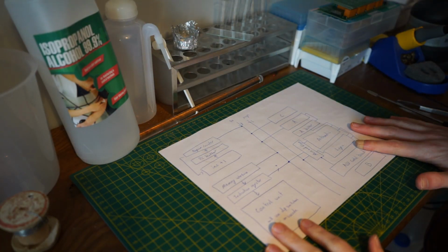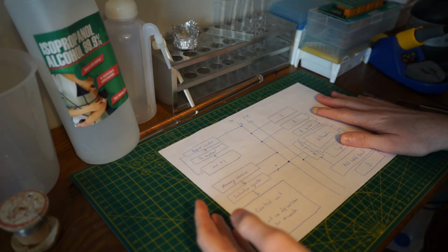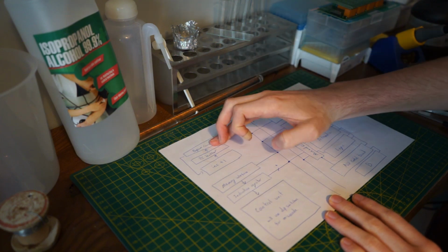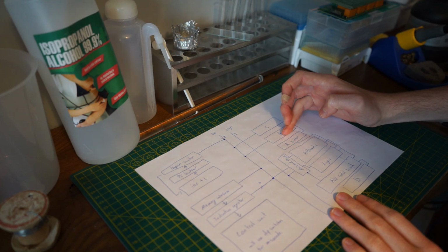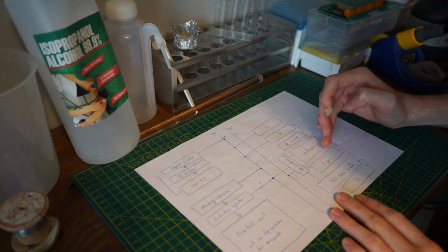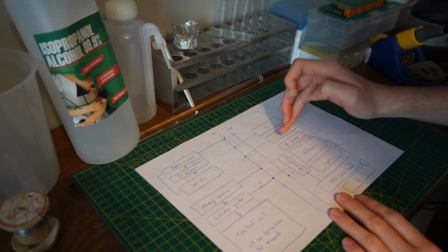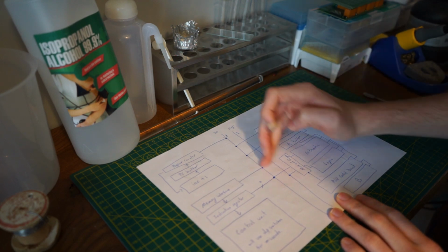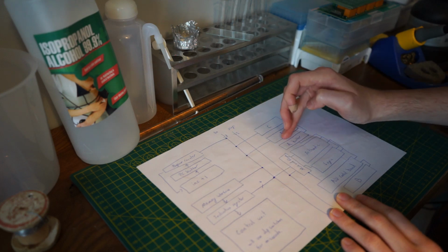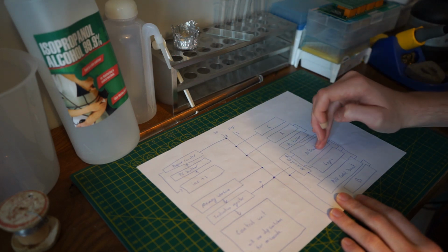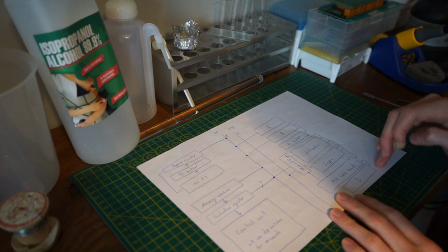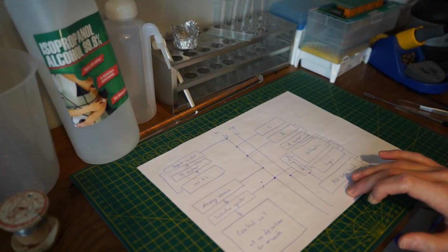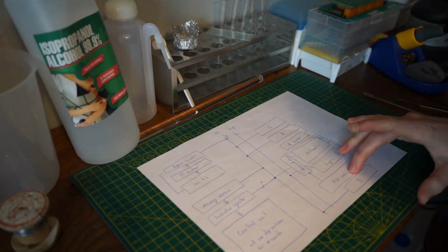So this is the architecture of the CPU I'm designing in relays. It will have an 8-bit bus and an 8-bit program counter. There will be a C register, an A register, and a buffer for the A register, so we don't get an infinite loop. A gets put into the buffer and then fed into the ALU, and then we can reset A and put the ALU's output into A without affecting the input to the ALU. Then we've got B, which goes into the ALU as well. That should also go to the bus. Just make that connection.